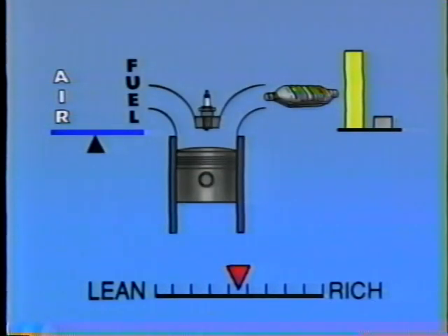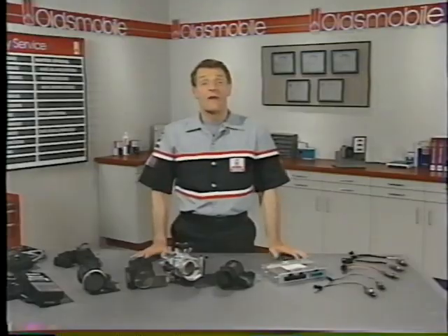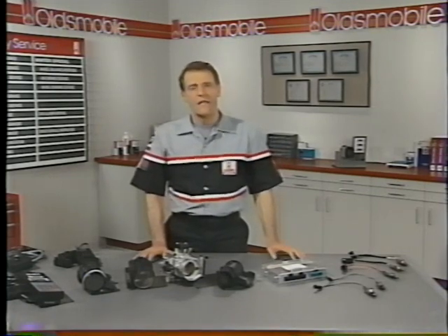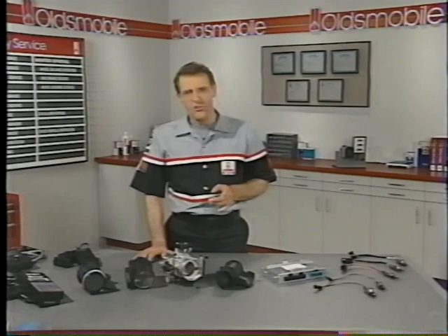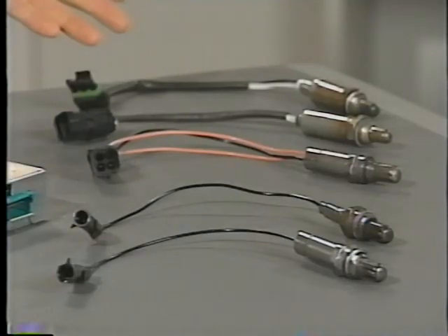Catalytic converters can function properly only when the amount of oxygen present in exhaust gas is controlled within a tight range. A deviation from the correct air-fuel mixture as small as 1% can degrade catalytic converter performance and increase exhaust emissions. To get that last bit of accuracy needed, the ECM or PCM needs to know how each calculation actually worked out, and that's where the oxygen sensor comes in.